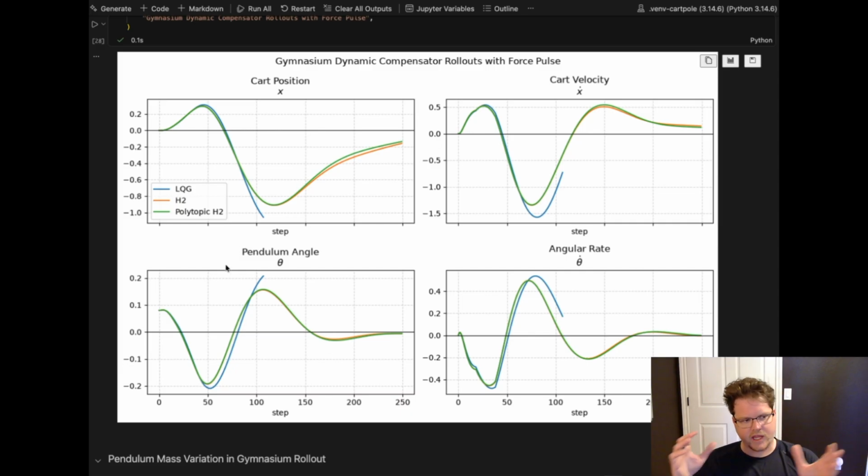Whacking the system, we have more of a discrete simulation. We have a quantization on the actual control itself, and it becomes more unstable. We are simulating it, so it's obviously in Gymnasium, by no means a Sim2Real platform, but you can only imagine with, say, a quadrotor or something like that, you have a mixer between the rotors or the motors that control the rotors, and all of that's nonlinear. So when you apply this command here for stabilization effects, you're not really modeling any of that. That's still down the pipe of the control.